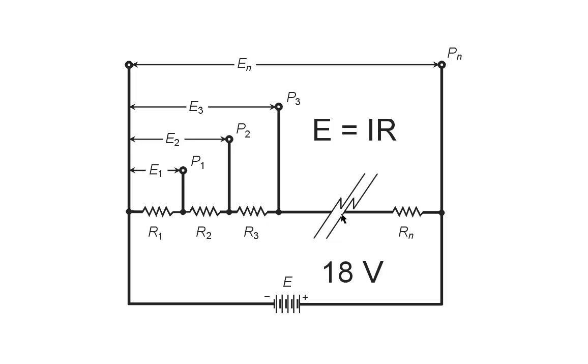All right, we've got 4 resistances. Each one of them is 9.0 ohms. We need to test out and see if choice D is actually going to give us the voltages that we want. So here we have 9.0 ohms times 1/2 of an ampere. I think you can probably do that in your head. That's going to be 4.5 volts. That's voltage E sub 1, 4.5 volts right there.